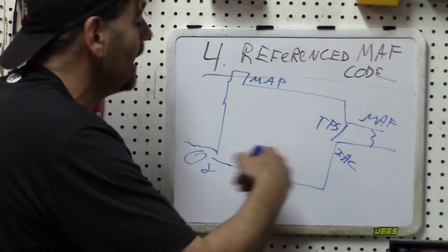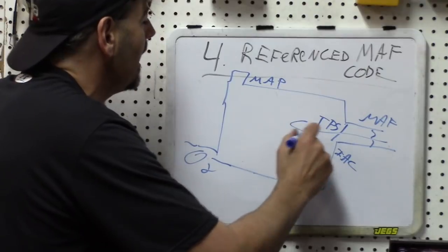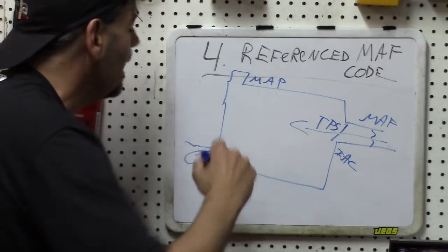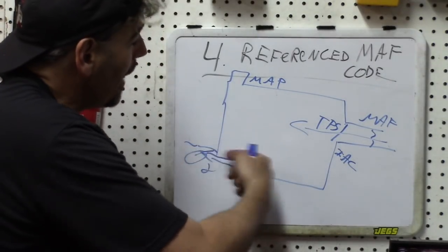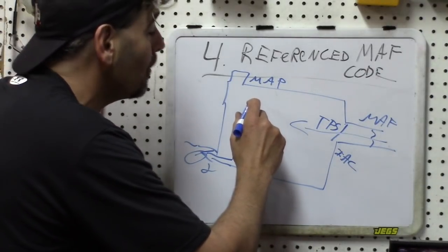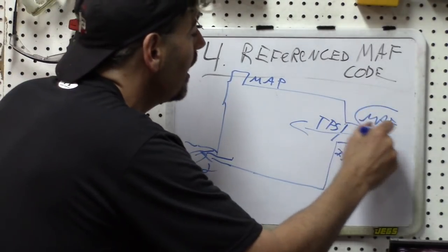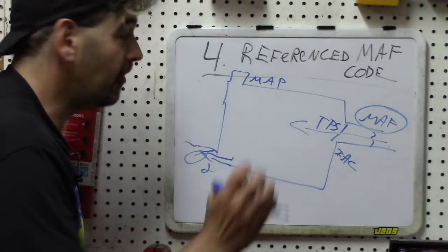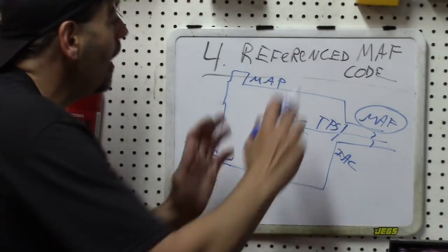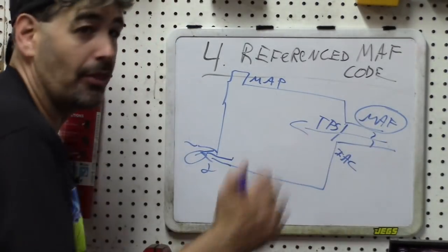In the Volkswagen, it was a timing problem because the amount of air coming in was not matching, obviously, the amount of oxygen measured at the exhaust, and it was because of a cam crank timing problem. One of the things we saw was a MAF specific error code, even though the mass airflow sensor was measuring accurately. There was nothing wrong with it.